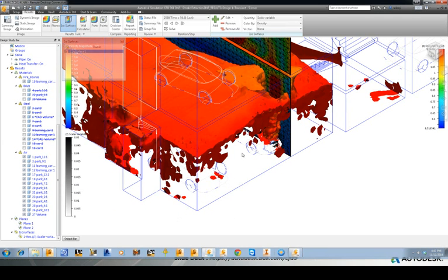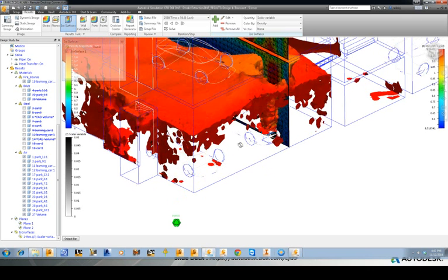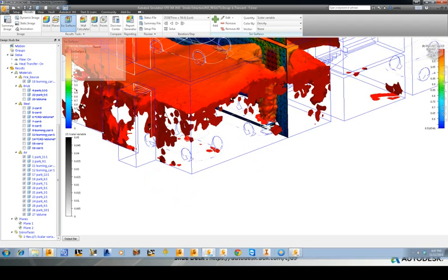We can see with ISO surfaces, I know this looks pretty terrible, but there's a reason for showing it, and that's because this ISO surface is hugely driven by the poor mesh as we move away from the fire. So there's blobs that, if we refine the mesh, wouldn't be there anymore, and this would all be much, much smoother. But for the sake of what I wanted, and probably for most analyses, it's okay.